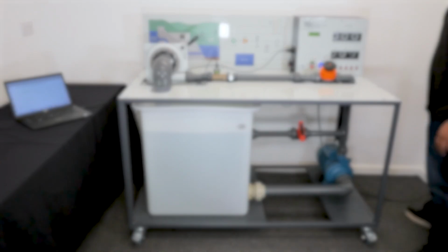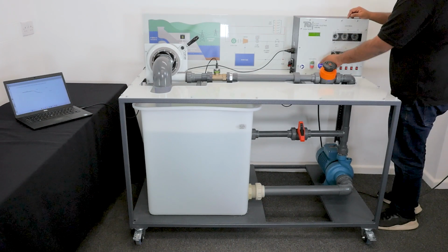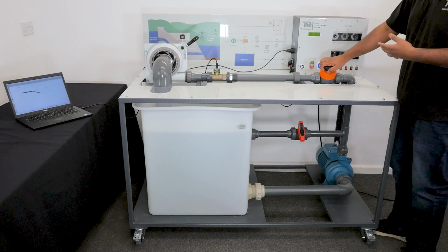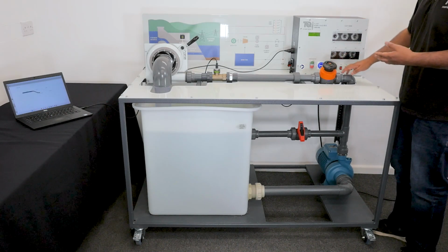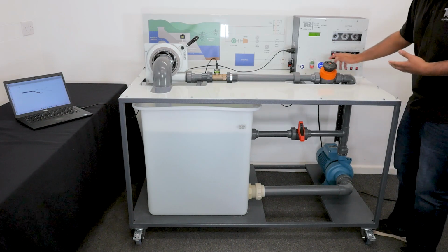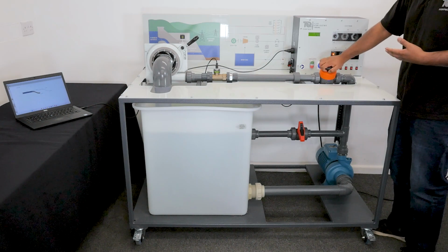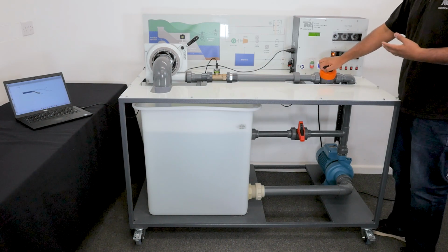In the first experiment we're going to look at, we'll be adjusting the flow rates. Start by making sure the turbine is set at 100% guide vane angle, then switch on the pump and start turning the valve slowly. Then engage one of the lamps and apply load. Now open the valve further and notice that the lamp starts to glow more brightly. We can see the voltage here is getting higher because more water flow is going through the turbine, so it's generating more electricity.